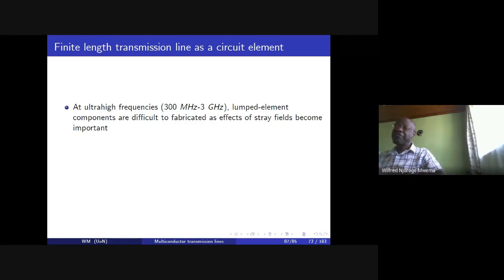Therefore at high frequency, a simple 1 kilo ohm resistor now starts looking like an RLC network, and at some given frequency, the network will resonate, and we'll see that we have an impedance that is very different from what we started with.